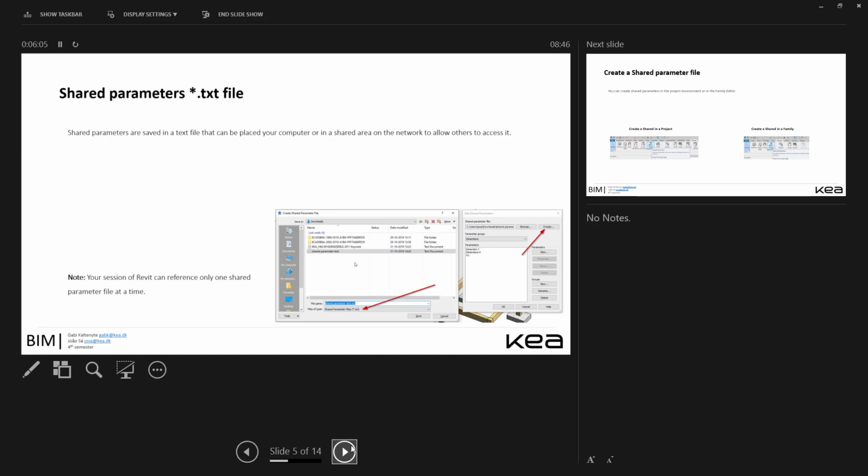Okay, so shared parameters are saved in a text file that can be placed in your computer or in a shared area network for others to allow access to it. Note, your session of Revit can reference only one shared parameter file at a time. It doesn't ship with a project. It's on your Revit session. So the same as you having your own shortcuts, you will have your own shared parameters. So you can only have one file of shared parameters inside your Revit session.